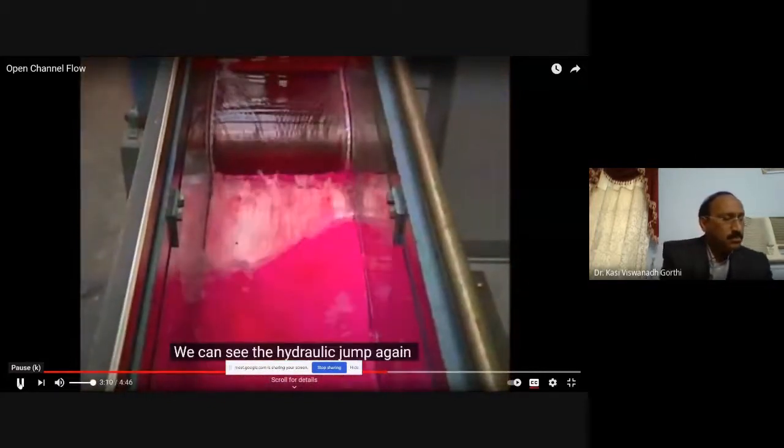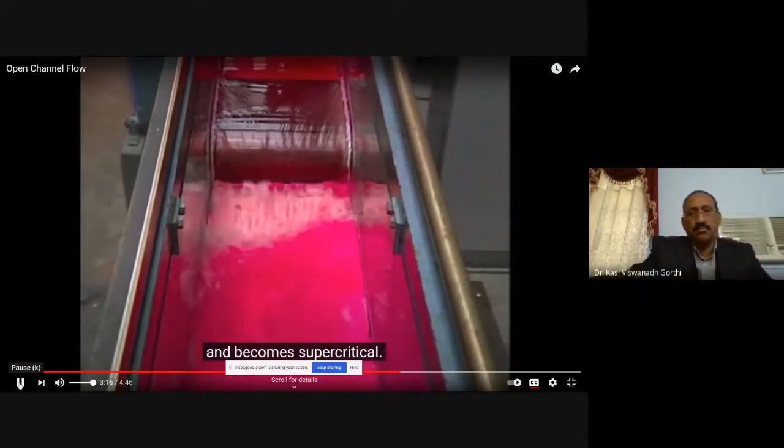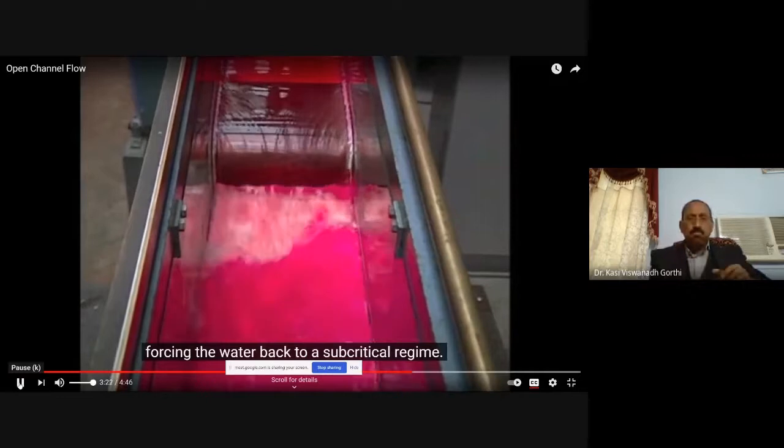We can see the hydraulic jump again in the laboratory flume. Flow spills over the weir and becomes supercritical, but downstream the flow is restricted and a jump forms, forcing the water back to a subcritical regime.